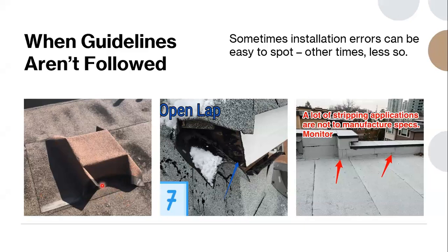So it is an area where water can get under here. In other cases, if corners are cut or if compatible products aren't being used, if guidelines aren't being followed, you might have cases where there's issues with adhesion and things are opening up like we have here. In other cases, it might be a little more difficult to identify if there is an issue with the installation.